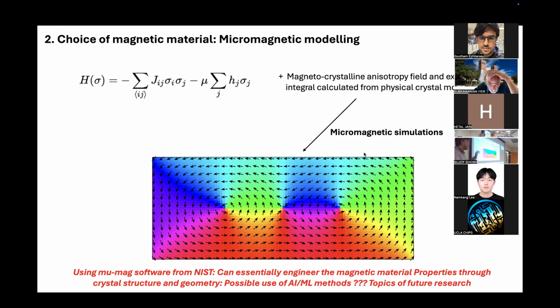And also, if you look at a lot of ferromagnetic materials, people have initially tried nickel and cobalt and nickel iron, but a lot of research has been looking at using alloy metals like cobalt, zirconium, tantalum or something, right? And it turns out that alloy ferromagnetic materials can have a high permeability, high frequency operation, and also a high resistivity, right? So there's also a lot of research that needs to be done in material science to figure out new kinds of ferromagnetic materials that are better than the ones we currently use.